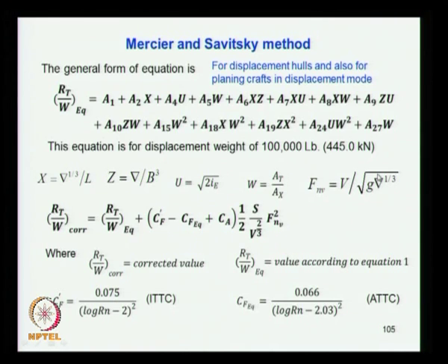So all these methods are basically meant only for design purposes. The final thing, you have to perform a model test, then you have to estimate the resistance before finalizing the resistance and the subsequent determination of the engine power and its selection.